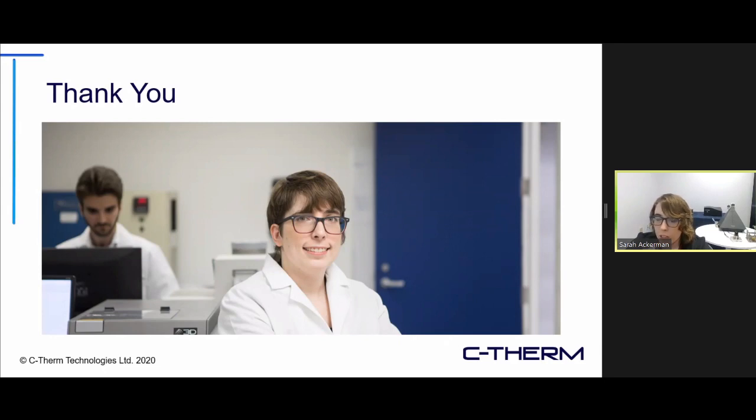However, there are other photothermal methods that we actually do use on an internal basis, like using a photothermal camera, like an IR camera on cycling. And that's a very good complementary technique. It's also a very good approach. This talk is focused mainly on thermal conductivity methods. The only reason I didn't mention the IR thermography types of methods with IR cameras, when you're operating the device to spot hotspots, is just because it's outside of the scope of the talk, but it is a good approach.